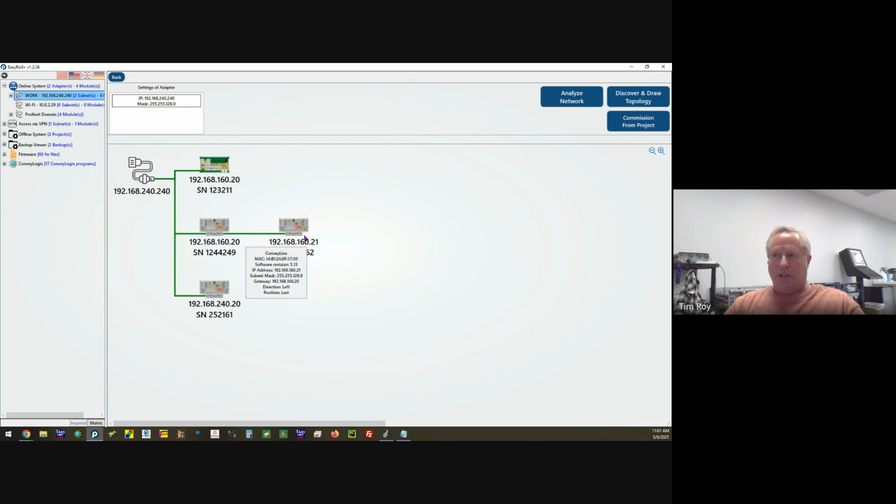Do I have a connection on my right port? No. That means I'm the last card in the network. Set a bit, the last flag. Now our network is properly auto-configured. We have incrementing IP addresses, the same subnet mask, the same configuration ID, a first flag and a last flag.